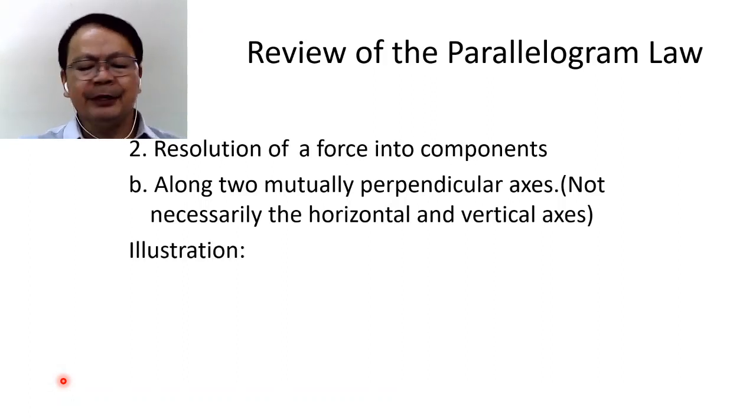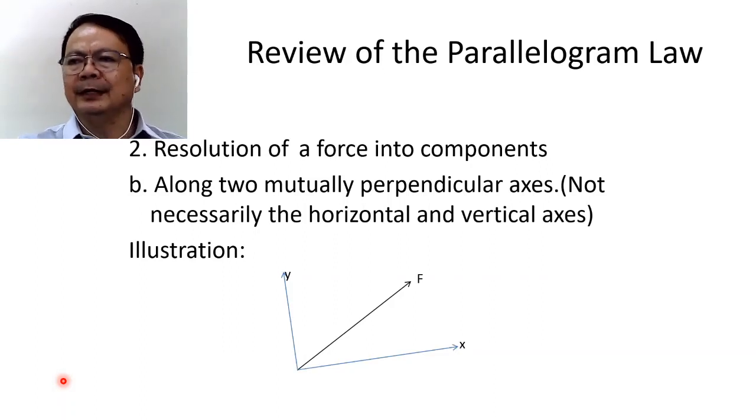So let us have here the illustration. Assuming that we have here our force F, and we want this F to be resolved into x and y, the two axes are perpendicular, but they are not necessarily the vertical and horizontal axes. It is very important that the direction of F with respect to either x or y must be known, such that this angle, assuming that this angle is the direction that F is making with respect to the x-axis, and therefore what we do is draw the parallelogram out of these forces.